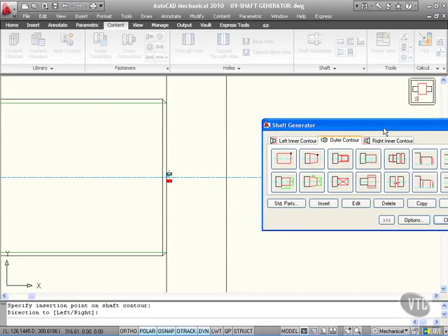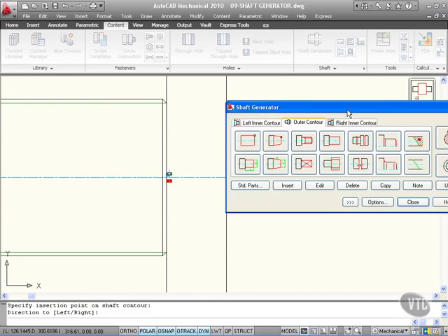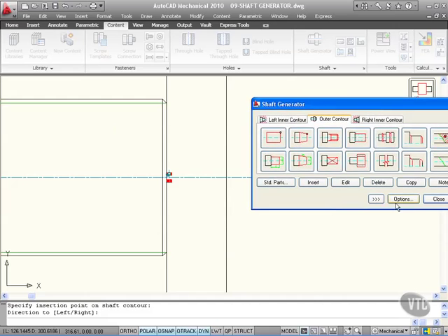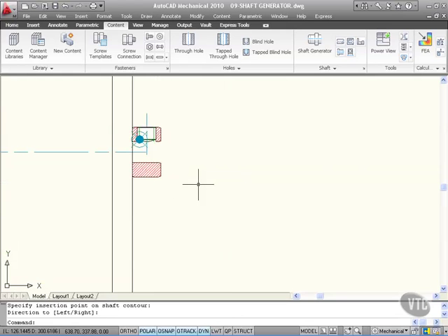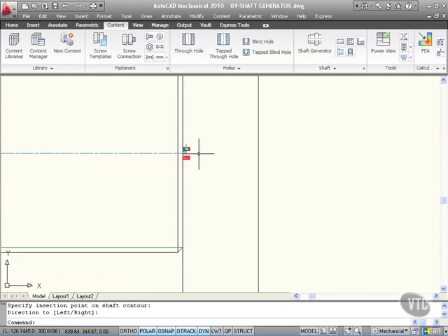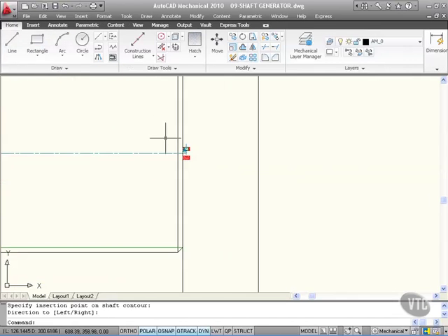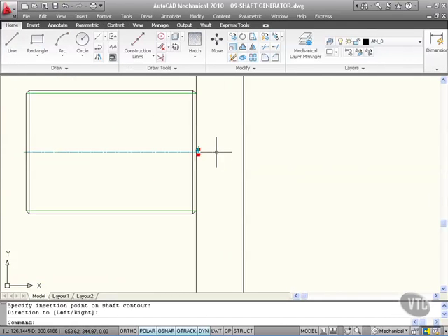And as you can see, it's a bit small, so I might need to scale that perhaps. Well, let's do that. Let's close that now. It's very small indeed, but I can still scale it. What I can do there is scale that in the X and Y direction, or just go to the Home tab and just scale it generally. So what I could do there is scale it in the X direction first, maybe.